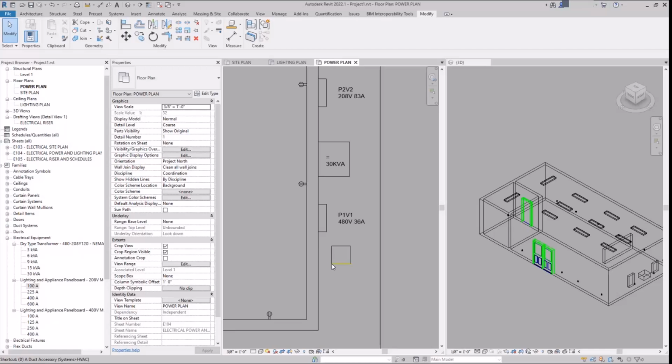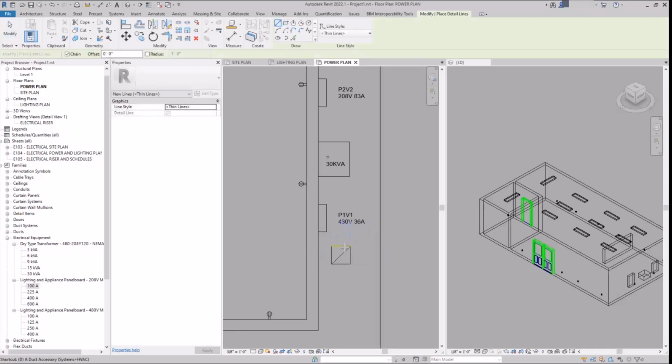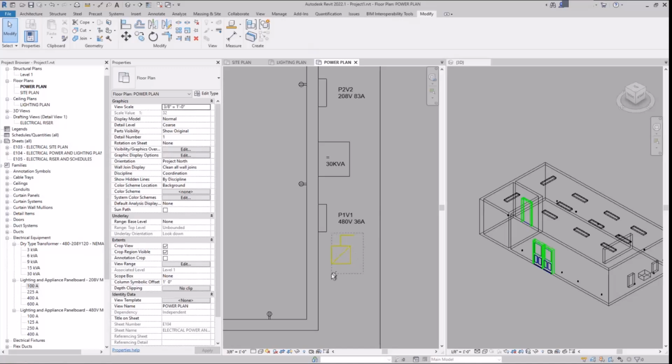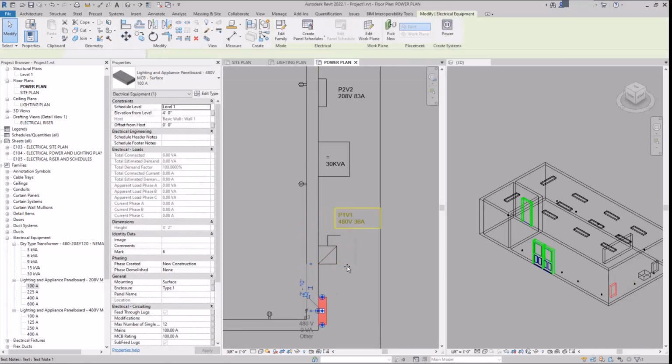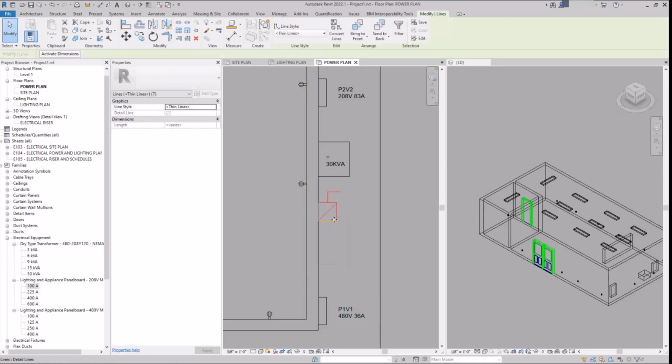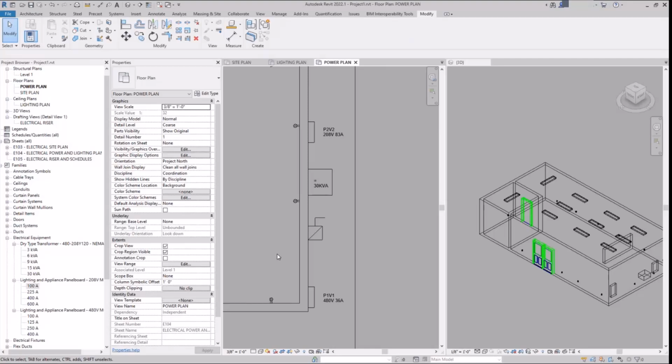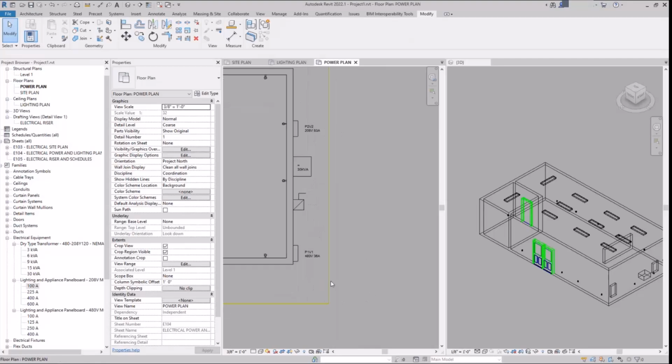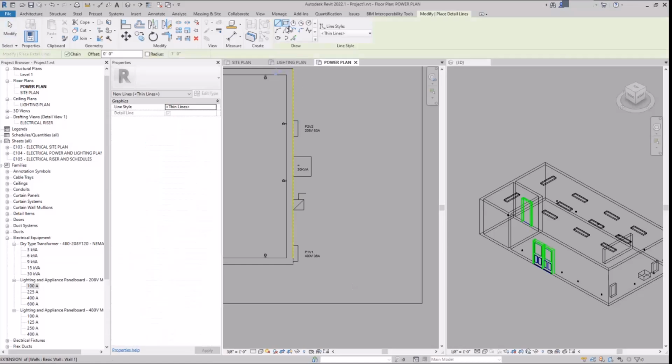I know a good example is some mechanical equipment you can't always get in 480. It doesn't happen often, but sometimes it's like, okay, they only have 208 available or whatever, but we only have 480 on site. So in that case, what would the electrical have to do? What would we have to do to be able to provide power to that piece of equipment? Yeah.